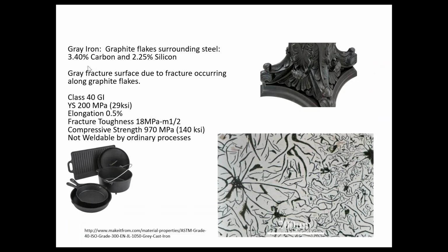Cast iron, on the other hand, goes back 2,000-3,000 years. And in fact, I was just in Pennsylvania at the Mount Vernon furnace, which was operating during the Revolutionary War. It was a stone furnace that basically operated just like the small cupola you saw. Because when you use charcoal or coke to melt iron and iron ore, what you end up with is the iron or steel absorbs the graphite. So you have about 3.5% carbon that gets absorbed. And when it solidifies, that graphite forms a continuous network of these flakes.